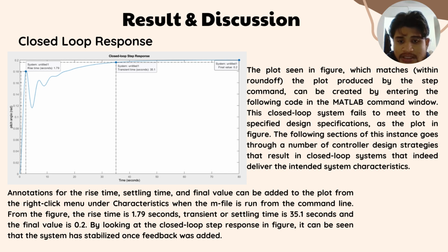From the figure, the rise time is 1.79 seconds, the settling time is 35.1 seconds, and the final value is 0.2. By looking at the closed loop step response in the figure, it can be seen that the system has stabilized once feedback was added.